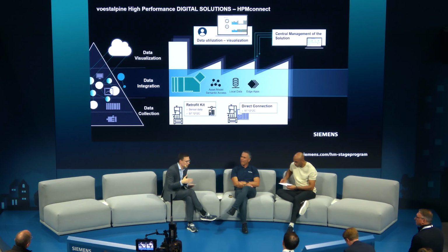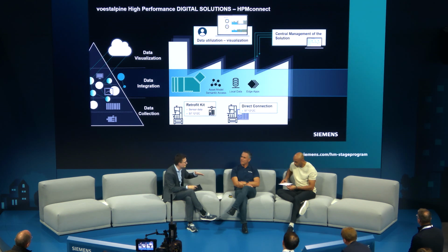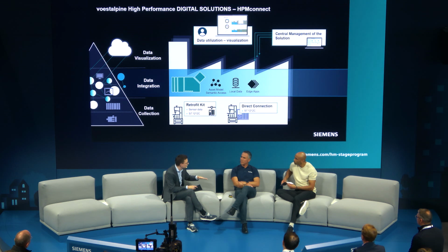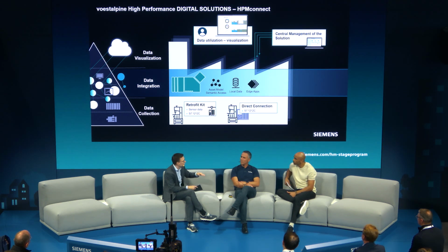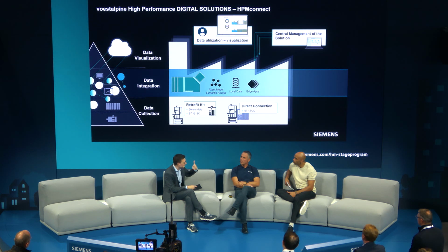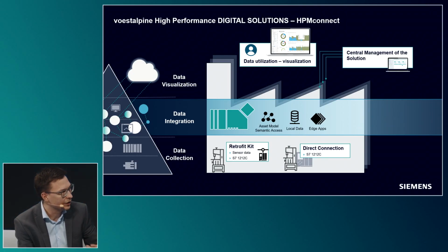When you go deeper in the solution, we start on the lowest end where we integrate PLC data, raw data signals, and sensor data. That data will be offered on OPC UA interfaces to collect on the edge device layer. Here we host different applications to transfer the data, interpret the data first, and transfer the results further to the cloud, where we host already different applications to utilize the data which we have collected.